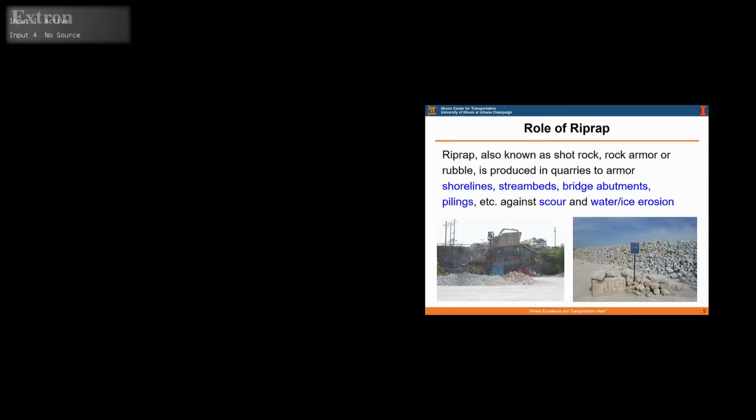So the riprap material, like in the figure, is actually the most common type of large-size aggregate we have in industry, and the most front-end product at quarry sites. These pictures were collected last summer in a field trip we made, and that's actually the typical quarry operation, using a crusher to crush the crude stones into different sizes. And the different sizes controlled by the crusher setting are separated at the quarry site into R1 to R7 with increasing particle size.